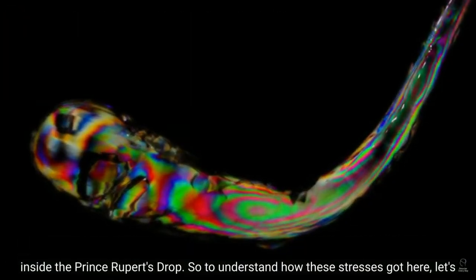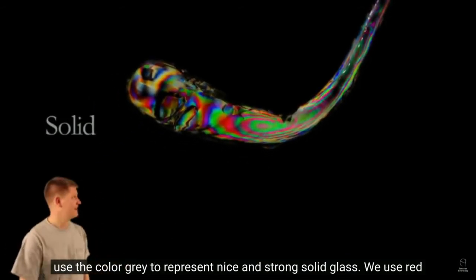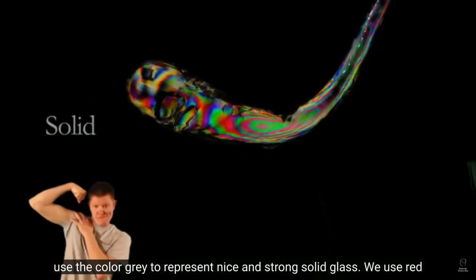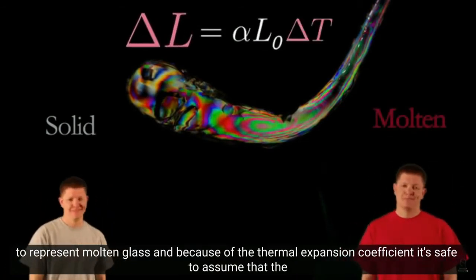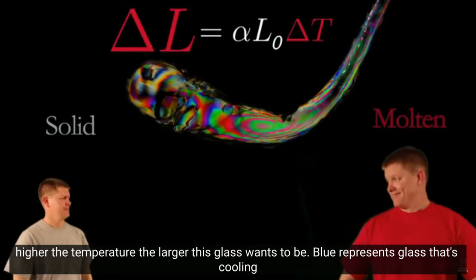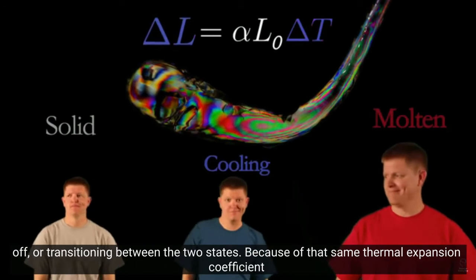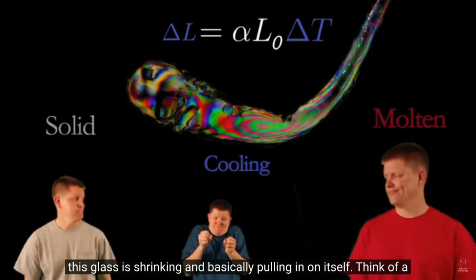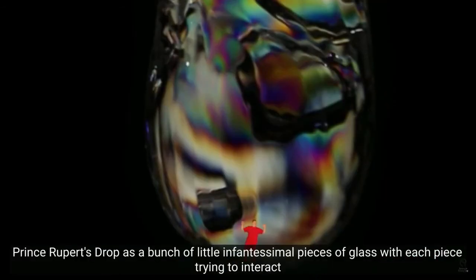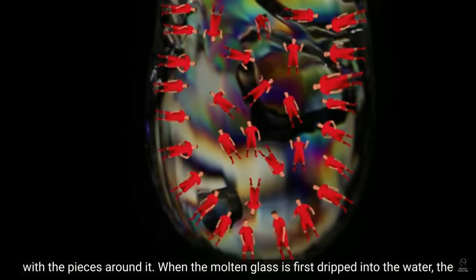So to understand how these stresses got here, let's use the color gray to represent nice and strong solid glass. We'll use red to represent molten glass, and because of the thermal expansion coefficient, it's safe to assume that the higher the temperature, the larger this glass wants to be. Blue represents glass that's cooling off, or transitioning between the two states. Because of that same thermal expansion coefficient, this glass is shrinking and basically pulling in on itself. Think of a Prince Rupert's drop as a bunch of little infinitesimal pieces of glass, with each piece trying to interact with the pieces around it.